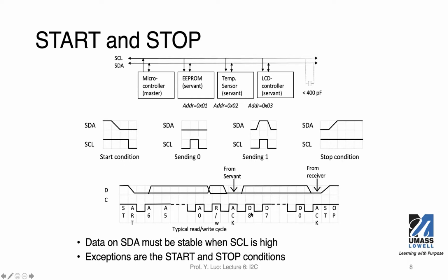Once these 8 bits are received by the receiver, it should acknowledge, which means pulling the data bit to 0 to acknowledge that.